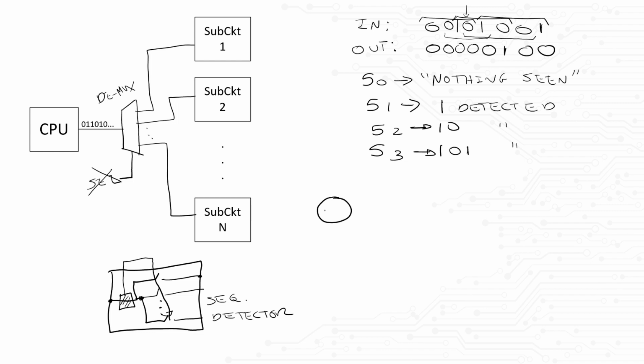If we start at S0 and our next input is a 0, then we stay at the state. However, if we detect a 1, we can go to the state S1. In both scenarios, the output of the FSM will be 0. At S1, if we detect a 0, we can move to S2 where we said we detected a 1, 0. But if we detect a 1, remember that we said it will be an overlapping FSM. So that means we will stay at state S1 because we detected a 1, or the start of our sequence. Again, in both cases, the output of the FSM will be 0.